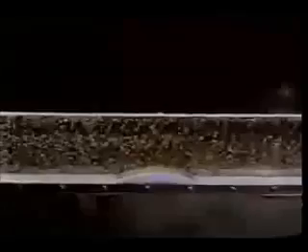To see how a jet develops, we'll watch the establishment of a flow with a single jet at a higher internal Froude number. Watch the region above the obstacle near the top surface. The fluid stagnates there. Then the stagnation region begins to spread upstream, ultimately forming a layer of fluid at rest with respect to the barrier.